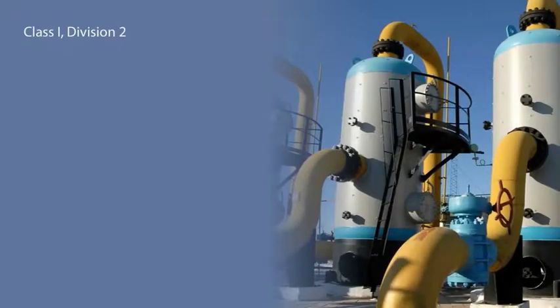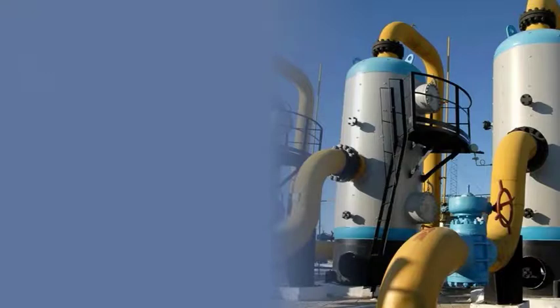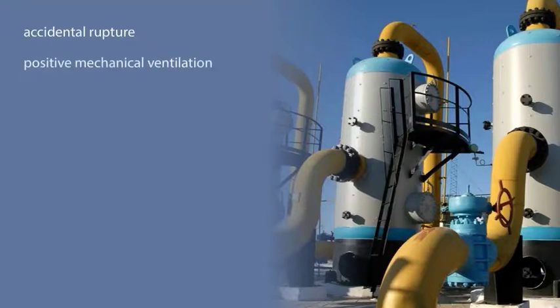Class 1, Division 2. Locations where volatile or easily vaporized flammable liquids and gases are handled and processed, but are confined in enclosed containers or systems. A hazardous liquid or gas would only escape into the air because of accidental rupture of the container or breakdown of the system. This class location is also an area in which hazardous concentrations of gases or vapors are normally prevented by positive mechanical ventilation, but that might become dangerous through the failure or abnormal operation of the ventilating equipment.